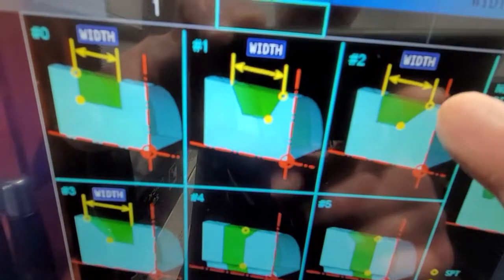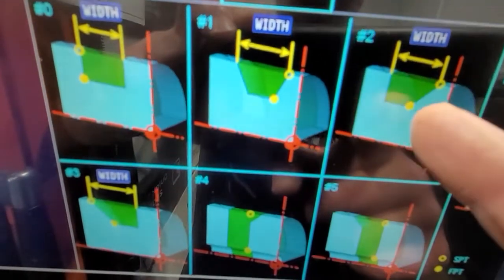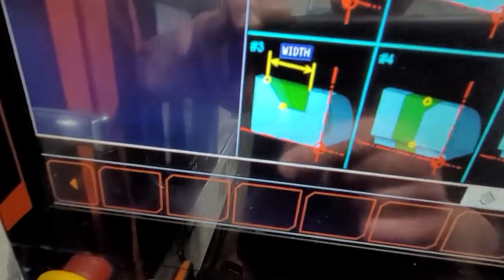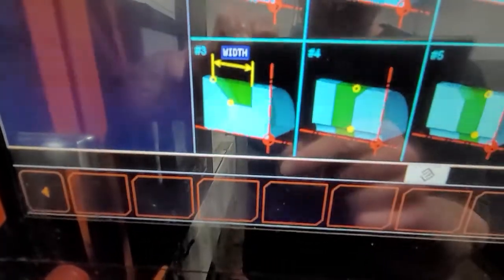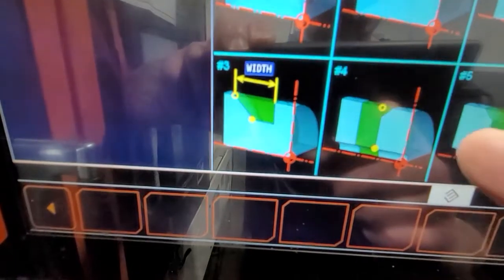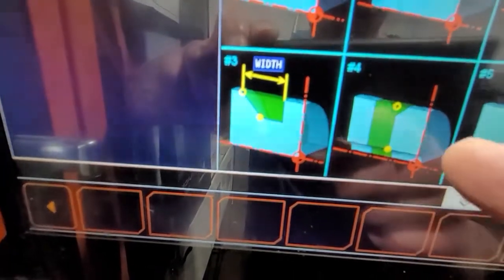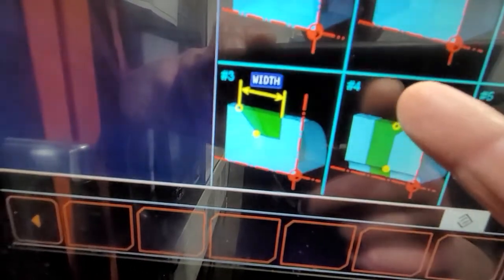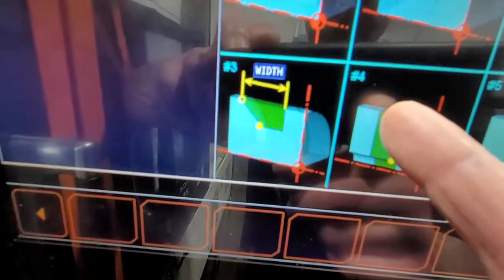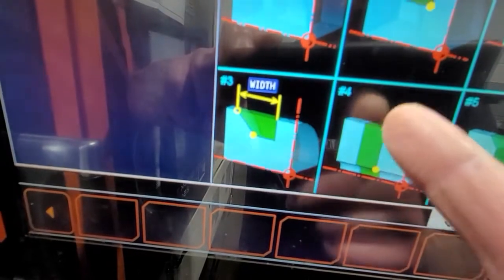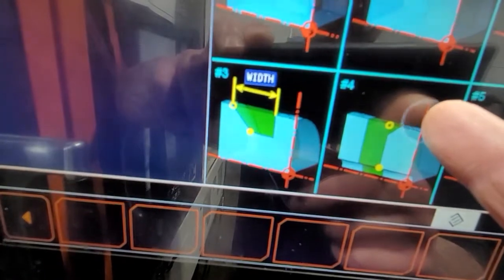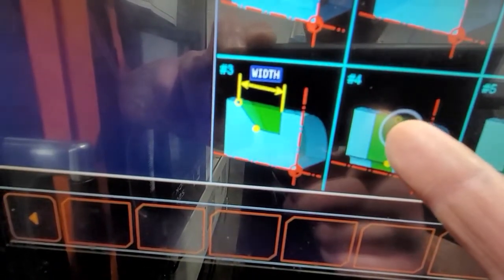Same thing, you don't do it at the beginning of the chamfer, you do it at the beginning of the flat on the bottom. Number three is the other side. Number four, I actually like this. Let's say, for example, when you're cutting off the part and you do want to chamfer. So what she does is she goes down straight, then she pulls up, turns a little bit to the right, then cuts the chamfer, and then continues back and cuts off the piece.